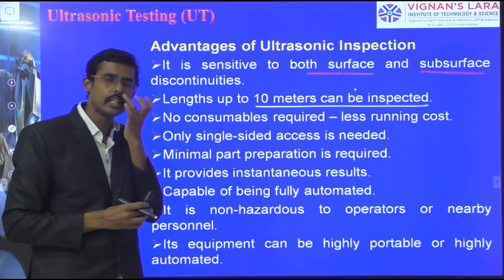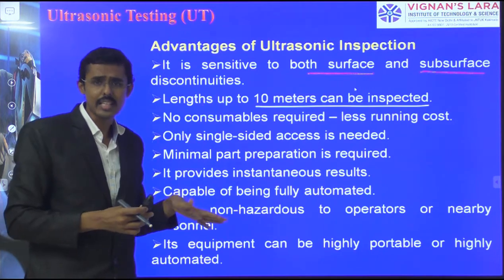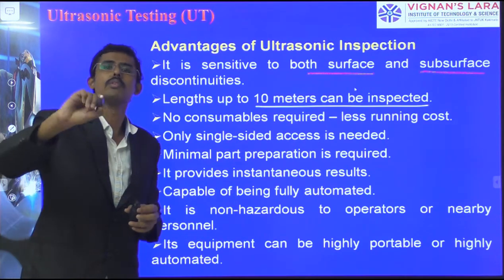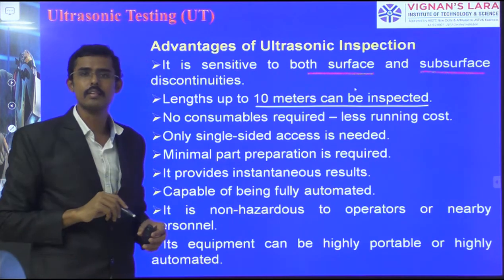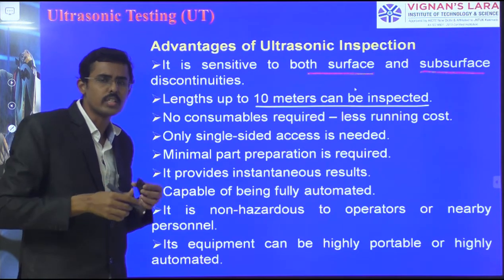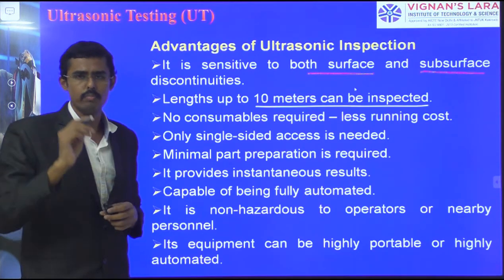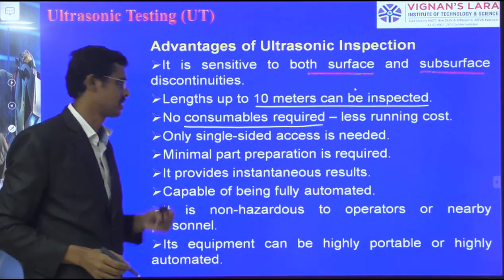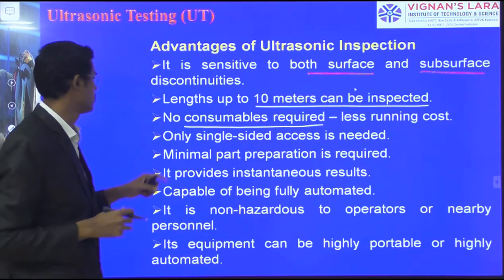So that creates a consumable. That film is considered a consumable, and such consumables are not needed here. We use a probe and keep it there, and a couplant is kept between the workpiece and the probe for contact. So very simple. No consumables, less running cost. A probe, and we use a little bit of lubrication.